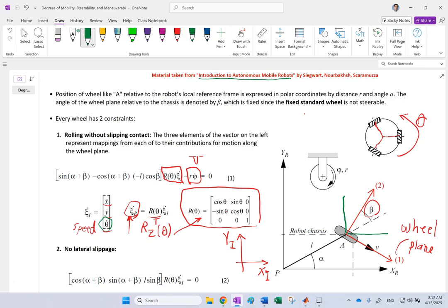Well, because this R frame is spinning with angular velocity theta dot, and the center of this wheel is not at the center, it will have a component v equals L times theta dot, correct? V equals R omega in spinning about the center. And that is, of course, going to be perpendicular to this line L. So there will be something like this component, and this is perpendicular to that. So there are three components.